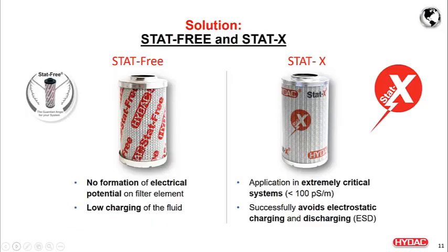In putting both technologies in perspective, stat-free utilizes media that forms very low to no electrical potential charge, and also has the same glass fiber structure that we used to have with the standard OptiMicron, and provides you the same level of filtration.